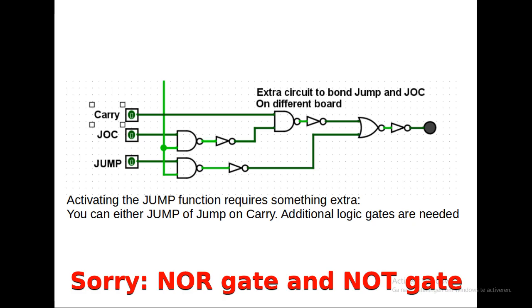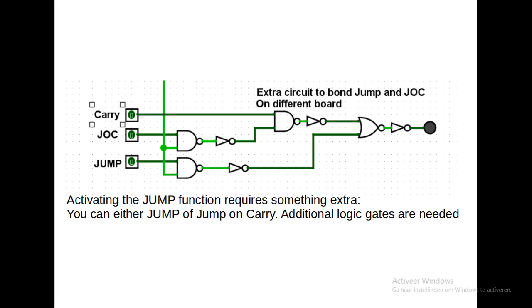One final note on the control system. You've seen that I used 16 control lines for this computer. In the future I will need more, because I would like to address RAM and ROM more extensively. For more control I can go as wide as I would wish to, but I think I'll go to 32 signals. That gives me some space in the ALU and also some space for RAM and ROM. I'm not going to build 4K RAM with transistors, if you don't mind.